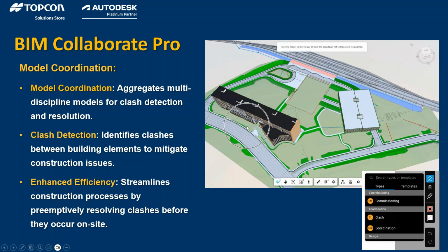So as you're working with the architect or you're working with owners, you're actually able to collaborate all of this information seamlessly and showcase it in a really nice previewer that's embedded inside the ACC. If you needed to, you can also locate and do clash detection and locate different coordination aspects within your site. So if you have a whole pipe network within Civil 3D, you can actually collaborate, clash that against the actual building locations, the tie-in locations, and you can make that seamlessly integrate with one another, before construction even starts.